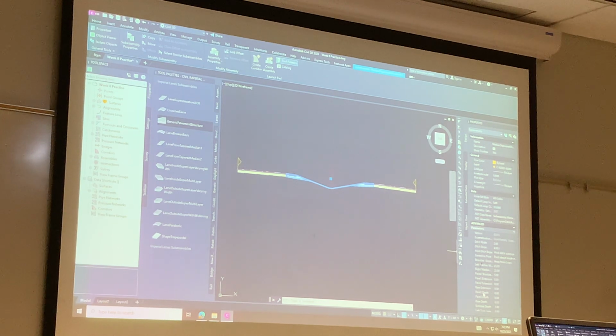Like these down here, paved one depth, extension, I just left those alone. The paved one extension and the paved shoulder width? Yeah, I left those alone. The shoulder, you've got your paved shoulder, you changed to 5. To 5. Yeah, to match the 5-foot shoulder.